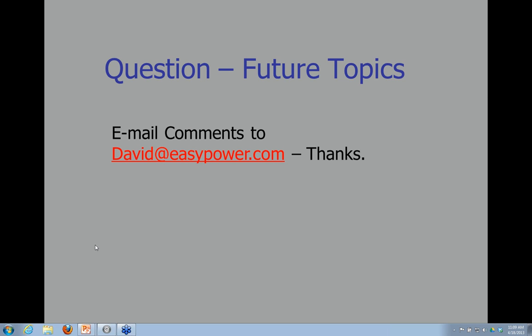Yeah, it does. It can be a little confusing to try to compare the two. In general, I've always used the interrupting report. And that's going to be more accurate because of the smart duty. That's what we call the smart duty function. And of course, it'll flag my one line, you'll turn red, for devices that are beyond the threshold. In the short circuit report, it's more of a general value for comparison purposes. If you were adding devices in the future, it just gives you a comparison point. It's always more accurate to do the equipment duty report.